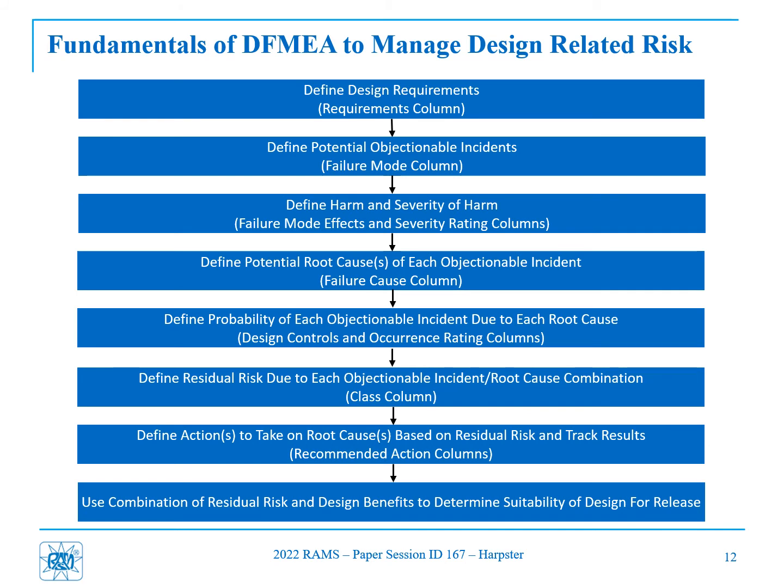So in the modern FMEA, what we do is we find the worst case harm with the worst case severity, and we assign that to all failure modes, even though we know we'll actually be overstating the potential harm from the design for that particular failure.